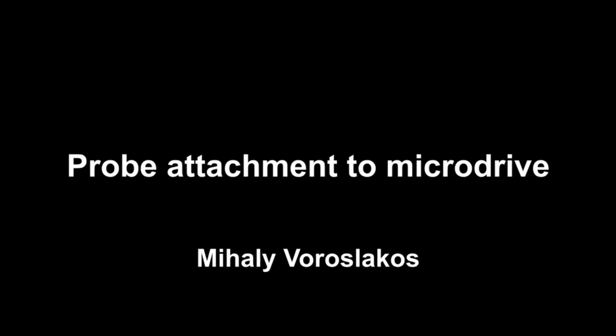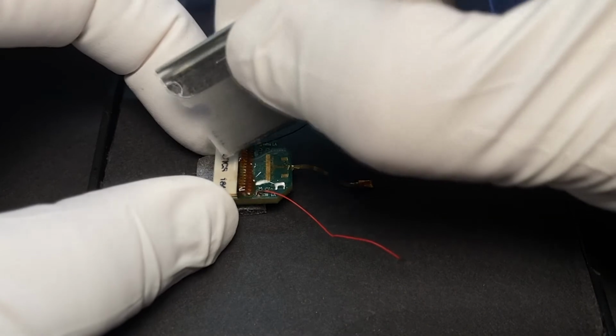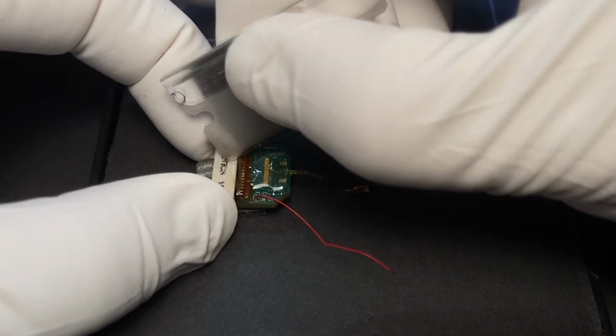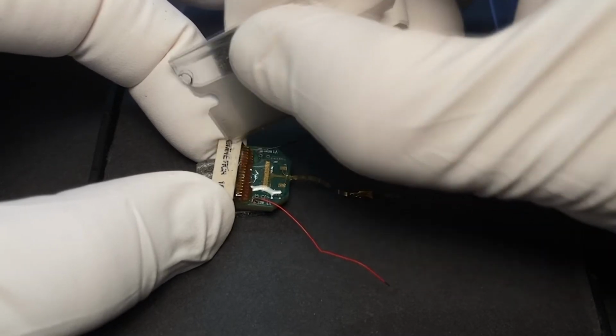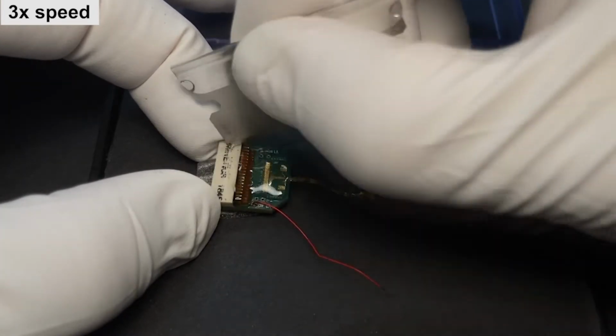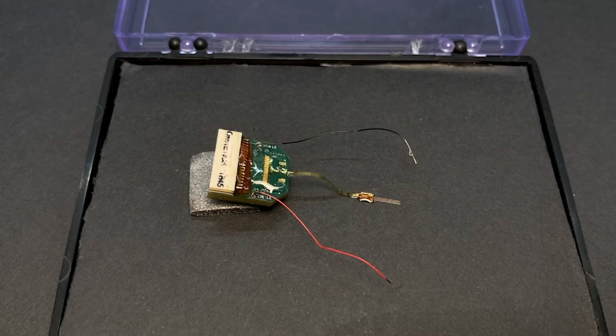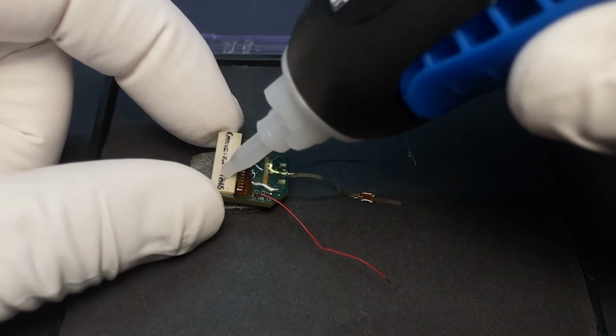And to do that, I personally prefer to attach a metal bar to the plastic Omnetics connector. So first I scratch the surface of the plastic just to increase the surface area of this connector. Please be extremely careful, because you don't want to break your silicon probe during this procedure. And then after you scratch the surface, you apply a small amount of super glue. And then you glue a metal bar into this